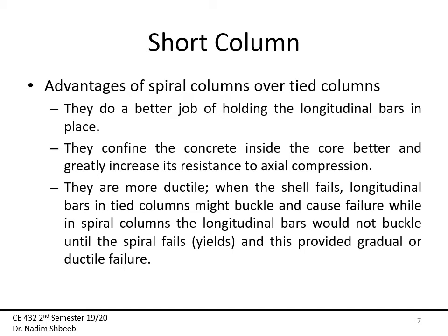What's the advantage of a spiral column, let's say, over a tied column? Again, with the spiral, because it surrounds the longitudinal bars much more effectively and efficiently than regular ties.